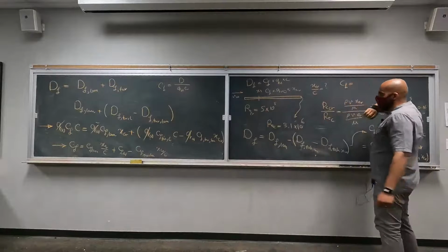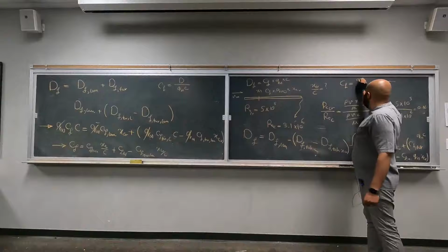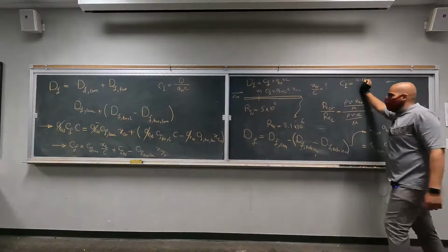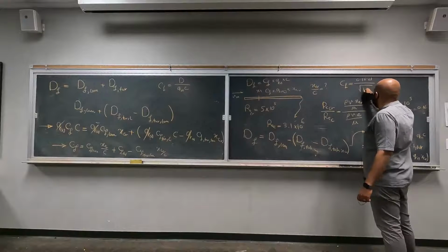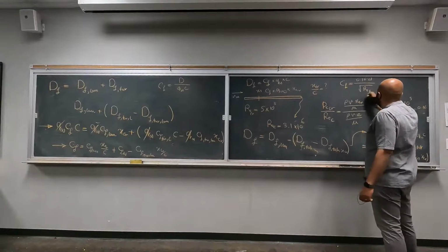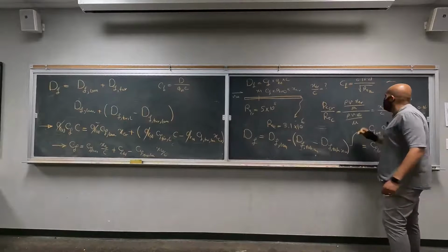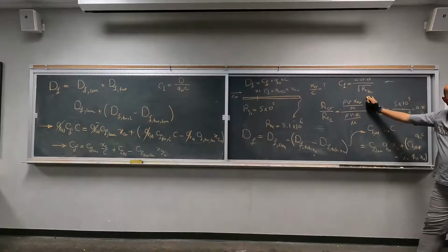What was the equation for the laminar CF? I don't remember. That's 1.1327, something like that, right? I don't remember exactly, but the square root of Reynolds number of the length, which is going to be the critical Reynolds number. So you plug that in, find the CF, right?